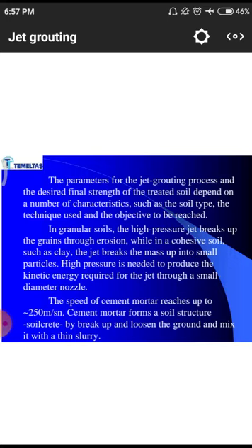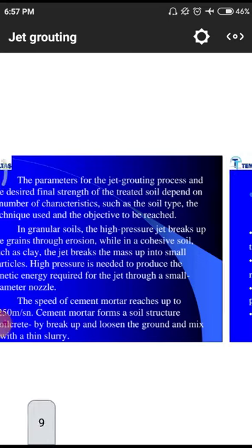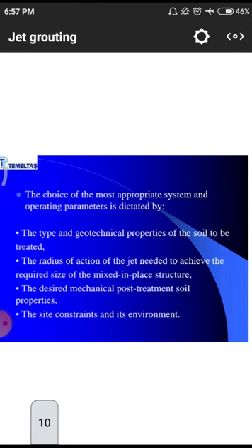Due to that pressure, some of the surrounding soil particles will mix with this cement, and they behave as soilcrete material. So by breaking up those materials, we have to mix them with the ground, and then we get a small scale of slurry, which is also beneficial to us for the purpose of obtaining strength.